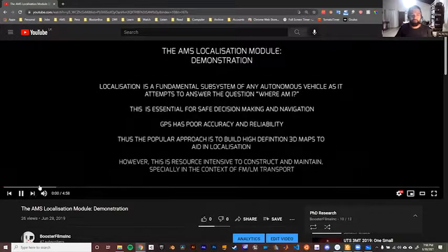In this video, you will see this is actually a Kalman filter based system. One practical thing you have to think about is that you have to pick your sensors very carefully. You need to make sure your sensors give more information and are very accurate, because the control information coming from the encoders and the IMUs is going to be very noisy. So you always have to pick very good sensors. Let me just show you guys.